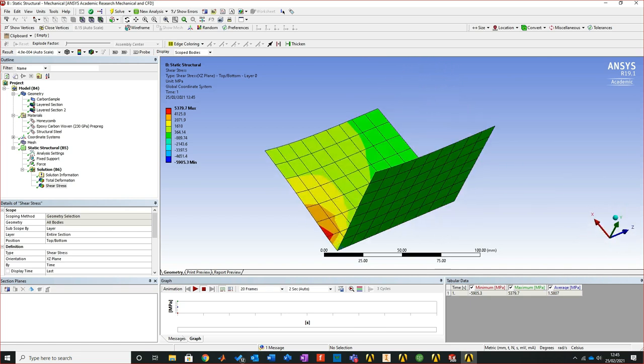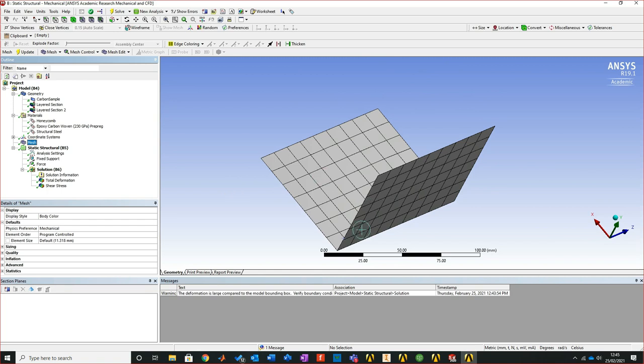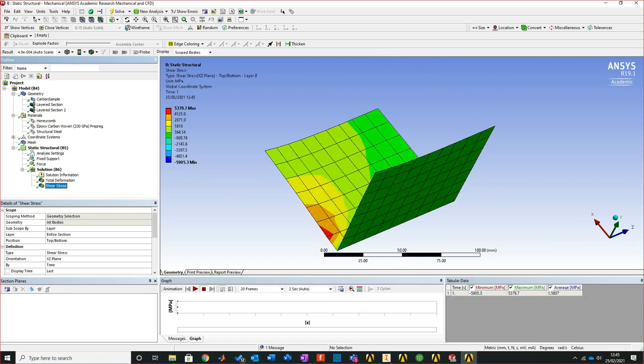And that is just really coming from this process here, but you can see there that there are concentrations here. I mean, the issue is my mesh is still quite large. It could do with being refined. Of course it could. But again, I'm just conscious that we're going to run out of time. And if I then look again, and now let's take a look at the YZ.